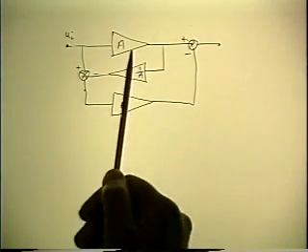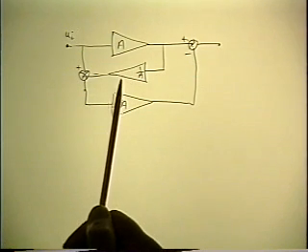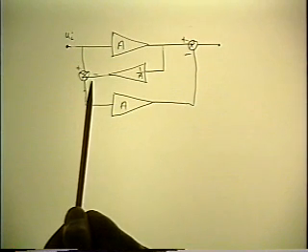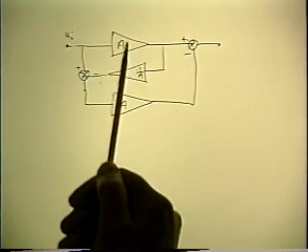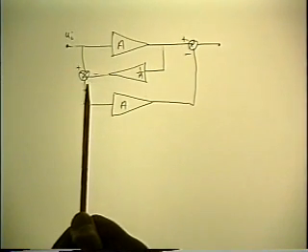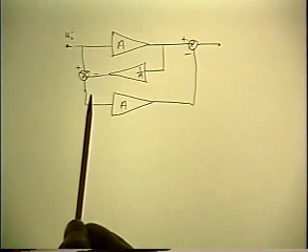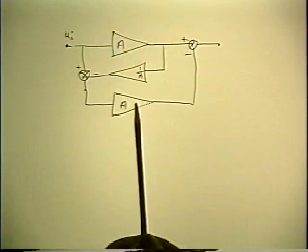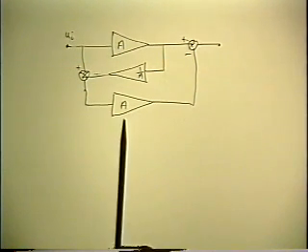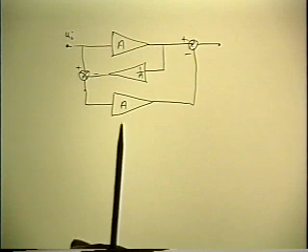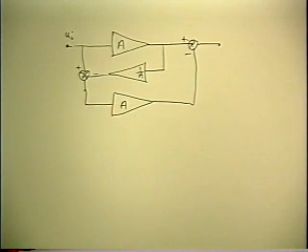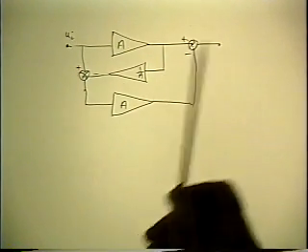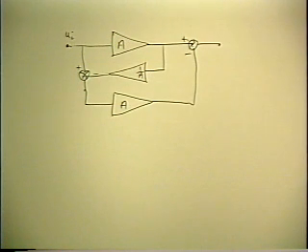Because what had happened was that the principle of his distortion cancellation was the subtraction of two equal quantities to give 0. Trouble is, you don't get 0 because you can't maintain the tracking. Because of the gain variation, the matching of the paths is not maintained. And it doesn't take much offset to get the distortion almost back up to where it was to begin with. It's the small difference of large numbers problem. Again, not once, but twice in the same system. He's trying to do 2 subtractions. No wonder it didn't stay put very long.